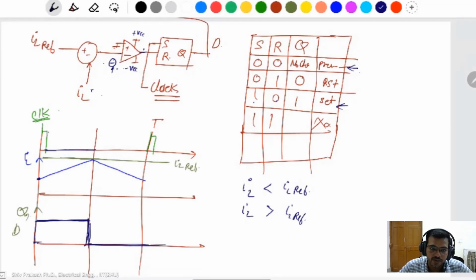Current control method. But sometimes if a disturbance occurs, if you fix this one, IL is fixed, and disturbance occurs, the IL duty cycle will be changed from lower to higher, then at that time the system may go unstable.